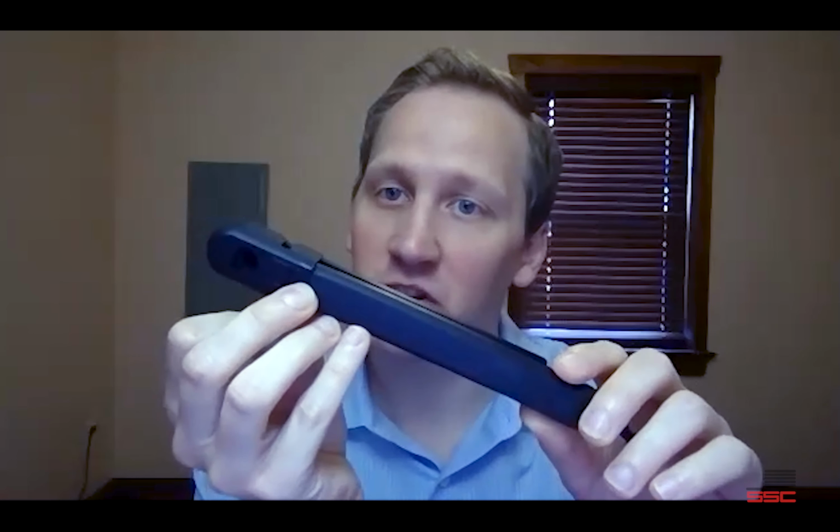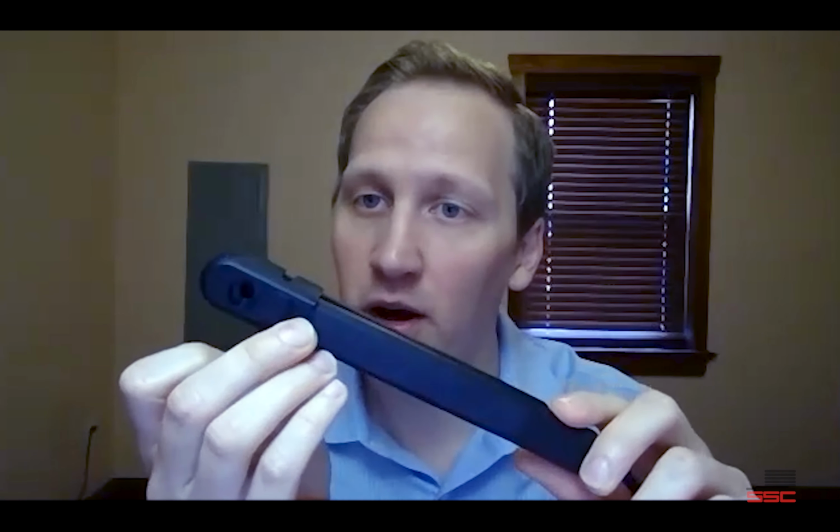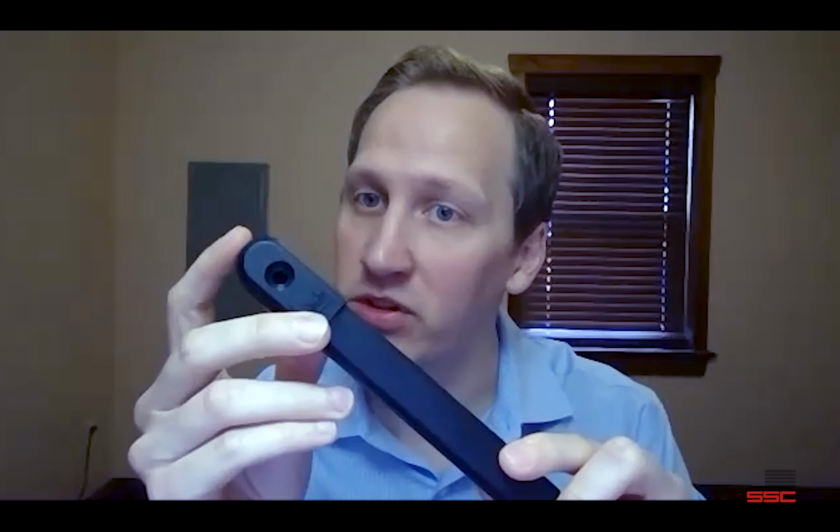The MG110 is actually one of our newer sensing edge profiles. It comes with a really nice cap system for mounting. The cap fits over the top of the sensing edge and the mounting channel. A self-tapping screw goes through this hole, into the channel in the back here, and then into your mounting surface. So it's a really nice, clean, easy way to mount sensing edges in areas where perhaps you don't have a lot of room. For example, in the draw-in post area on a slide gate, you might not have a lot of room there to mount a large sensing edge. So the MG110 would be a perfect fit for that kind of application.